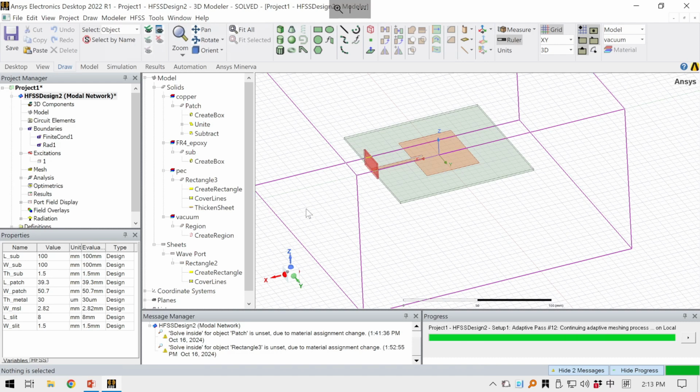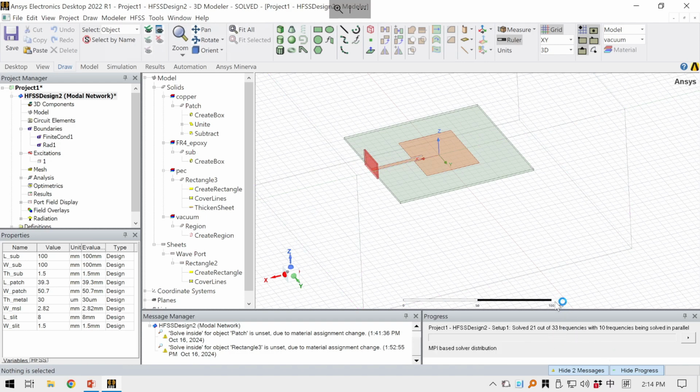That's the principle. If you put a lumped port, you can only treat this as a 50 ohm port, or you have to assign the port impedance on your own. But using waveport, you can later check, okay, is my port 50 ohm? How far is it from 50 ohm? This is a better thing.